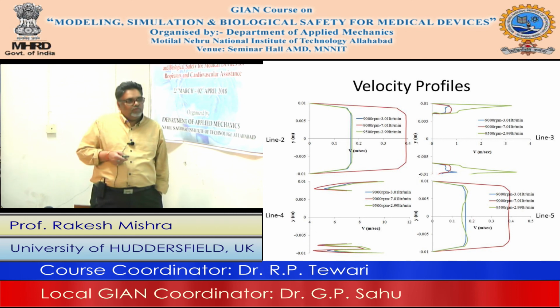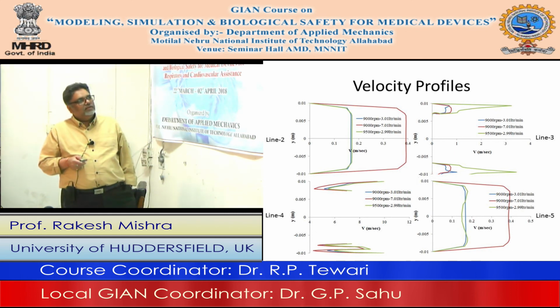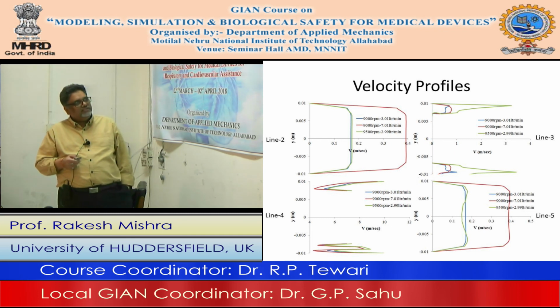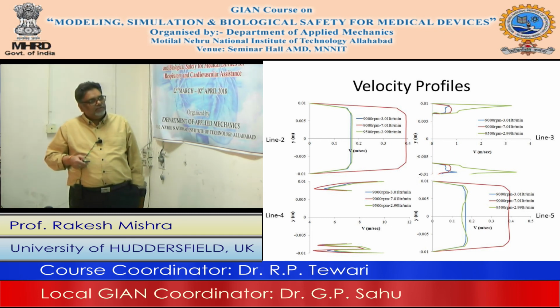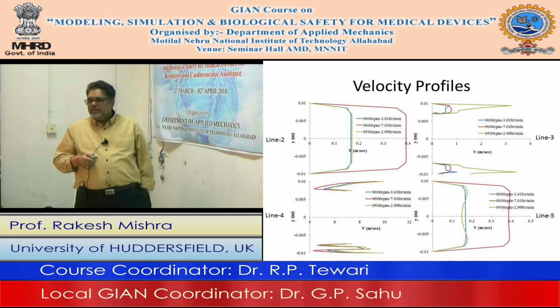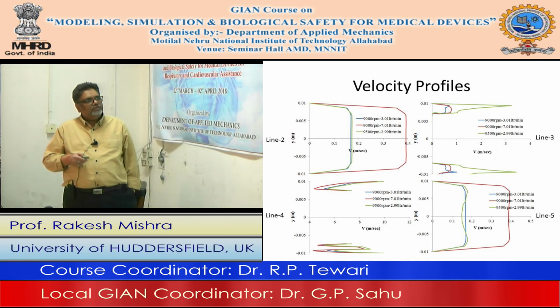Now, I was talking about wall shear stress. So you can say the magnitude of wall shear stress, the effect of speed is slightly higher here, or the effect of flow rate is definitely higher on this particular part. Turbulence intensity, the effect is a bigger zone here, the effect of flow rate is almost identical, although the magnitudes are different in the two cases.